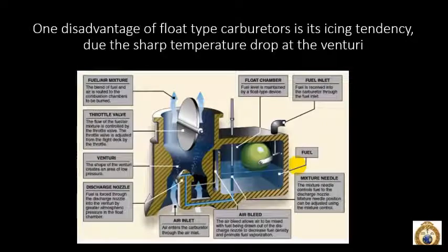So what we're worried about is condensation. A couple things going on here. This float chamber is actually vented, which means atmospheric pressure can equalize in here. This is why when the air comes in, it almost vacuums the fuel out for vaporization. So what we need to understand is as the velocity of something increases, its internal pressure decreases, and at this point the temperature actually gets colder.